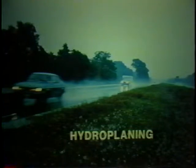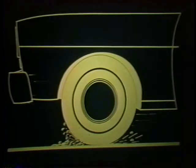Without drainage, a film of water lays on the roadway and can cause hydroplaning. When a tire hydroplanes, it rides on the water rather than the road. Steering control is lost because the tire-to-pavement friction is lost. Hydroplaning is a problem on any road where vehicles can travel at speeds above 40 miles per hour. So hydroplaning is not only a rural problem, but also one that can happen on arterial streets.